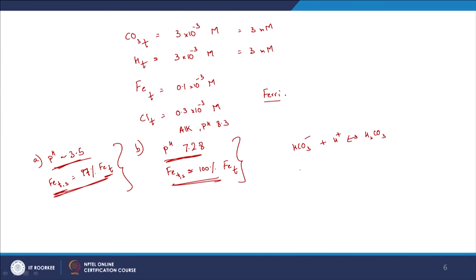Why is that? So here the key is to understand what we talked about earlier. How is this particular mechanism going to work? We know that there are two aspects, or three. There is charge neutralization, as in the colloids are negatively charged. So any positive charge that you add is going to neutralize the net charge on the colloids or suspended particles, allowing them to overcome their forces of repulsion. And the second aspect is sweep flocculation, as in now you have this Fe(OH)3 solid that precipitates out, that is what you saw here.